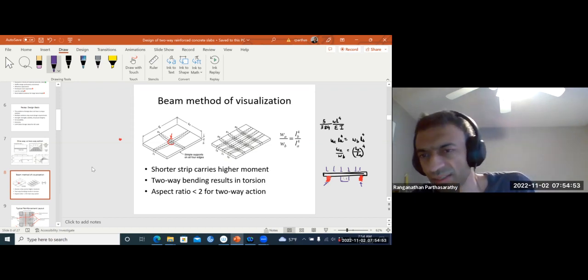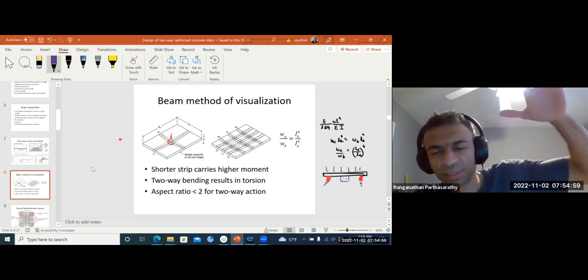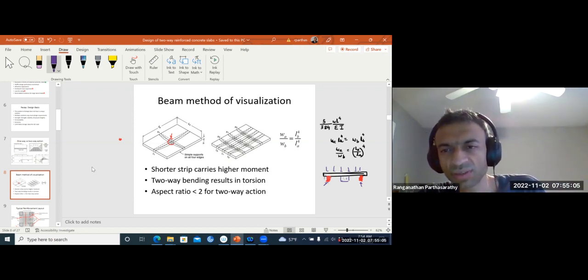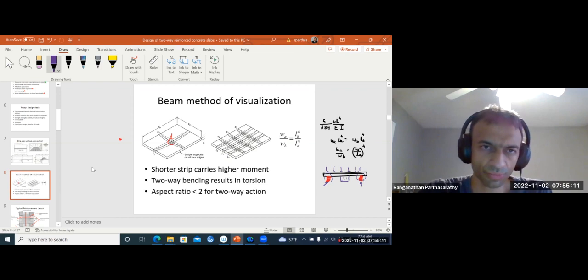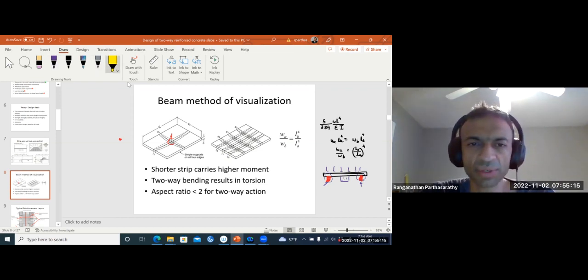If your bed is rigid, then it will compress everything through the same distance. So for the same displacement, the stiffer ones will offer a much higher load at the support. So the load is distributed in the ratio of the stiffnesses.